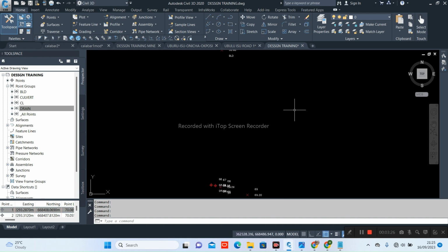The next thing is to see why it's important to group our points. After you have sorted your points and you are okay with their appearance, the next stage is to make the features show in the form of a drawing. You have to start drawing the culverts where they are located, based on the points: the shops, the buildings, the transformer if we have them.